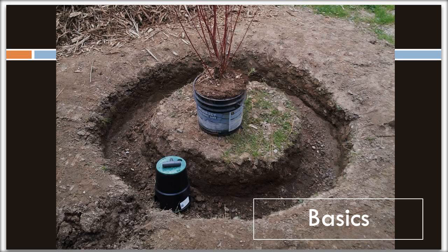Most people don't use this with drip irrigation. This is usually primarily used for a laundry to landscape system or a branch drain that comes from a shower or a sink. The water flows into the system, and this whole trench is filled with mulch. If you haven't seen any of the Greywater Action webinars before, there are laundry to landscape and branch drain webinars online, I believe, that you can learn more from.